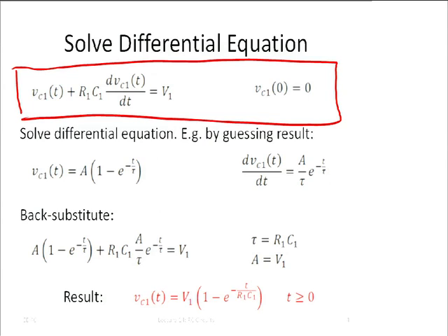I know that the voltage needs to start out at some fixed value, which happens to be V1 in our example, and then afterwards it has dropped down to 0. And e to the minus t over some tau, whatever that is. Just from units, there has to be something there. I cannot write e to the minus t, that is meaningless. I hated the teachers who did that. Is it seconds? Is it hours? So e to the minus t over tau.